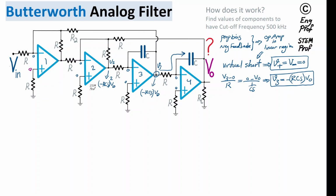Okay, so now we have V2 defined as a function of the output, and V3 defined as a function of the output. Now I can focus on finding the voltage at the output of op-amp 1, which I refer to as V1. I can simply write Kirchhoff's current law, or KCL: the current that is flowing in has no other way to go, so it should be equal to the sum of the 2 currents that are flowing out. I can refer to this as I1, this one is I2, and this one is I3.